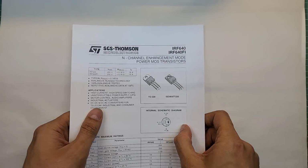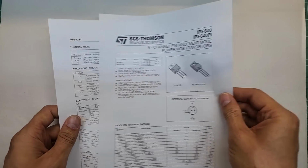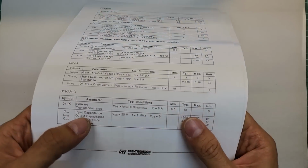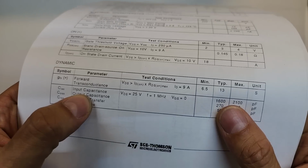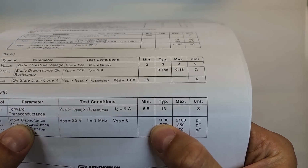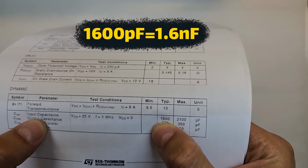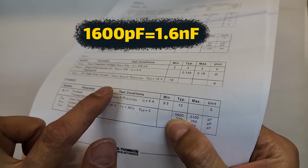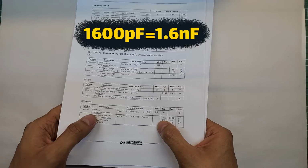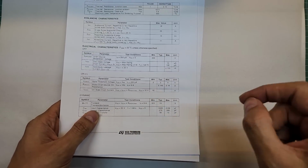This is the datasheet for the IRF640 N-channel MOSFET. Look at this table on page 2 here. The total input capacitance of this transistor is typically 1600 picofarads, which is equal to 1.6 nanofarads. In this scenario, it is really low and it is negligible in many cases. Not in all scenarios, but in many scenarios, this is a negligible and low value.